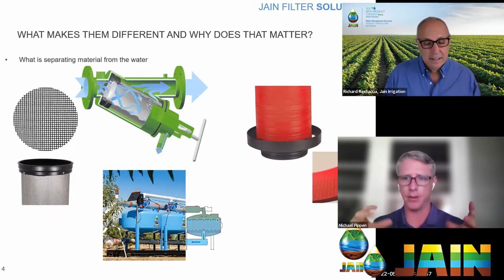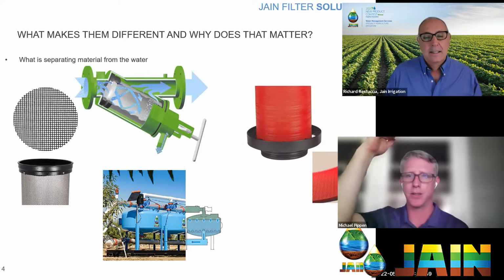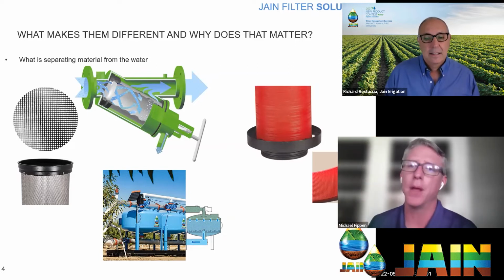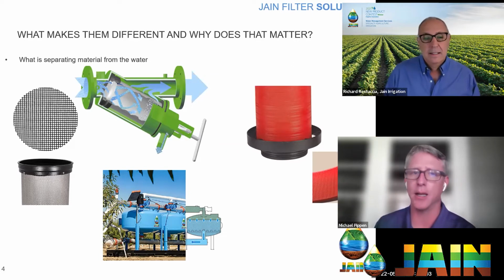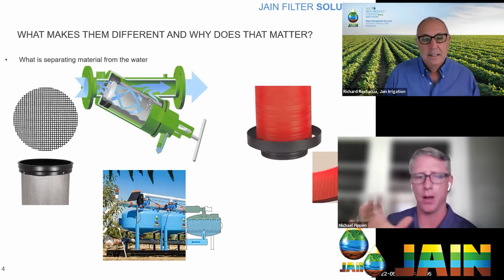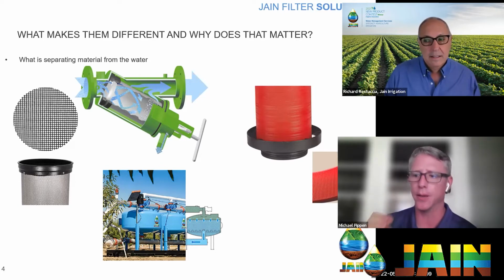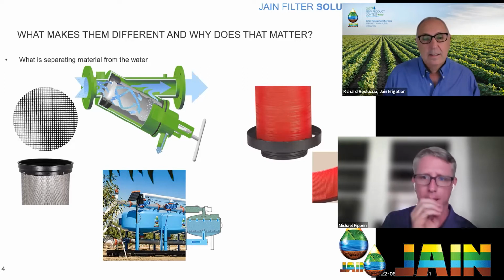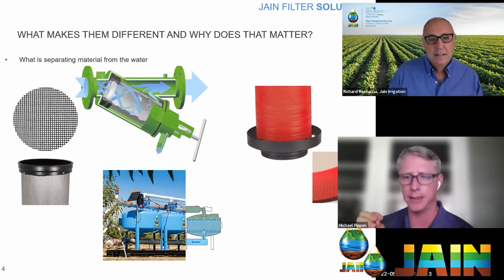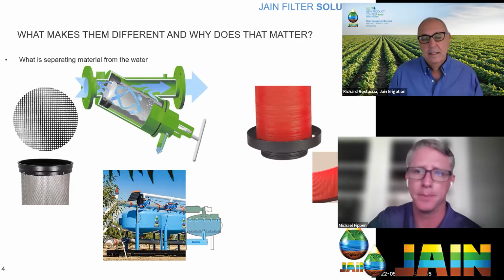Screen filters inside out, disc filters outside in, sand top to bottom. Really, the key difference in these is what is actually doing the filtering, right? In one case, it is a screen, in one case it is a disc, and in one case it's sand.